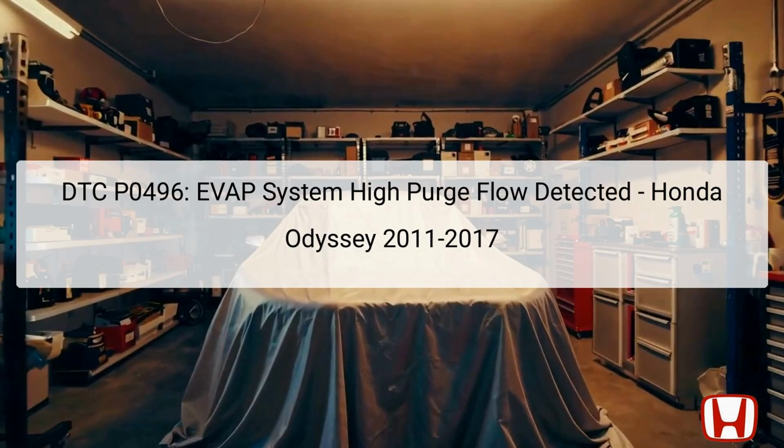In the Honda Odyssey from 2011 to 2017, key components involved include the EVAP canister purge valve, FTP sensor, and the PCM, or powertrain control module. The location of these components varies. For example, the EVAP canister purge valve is typically found mounted near the intake manifold, while the FTP sensor is usually located in the fuel tank area.